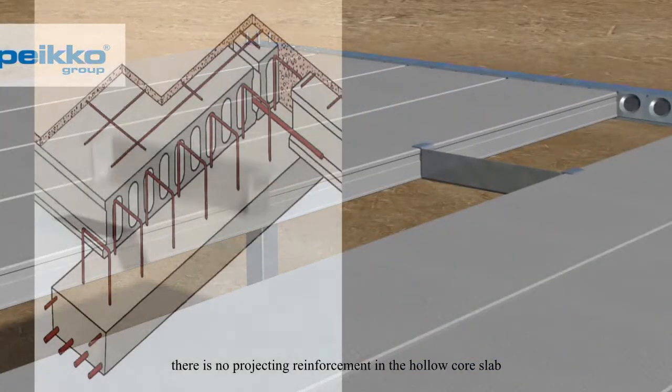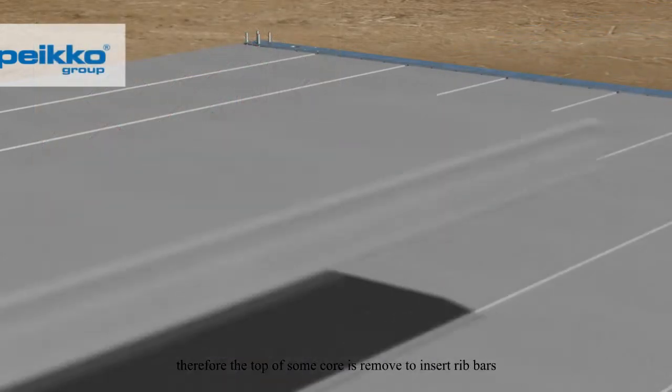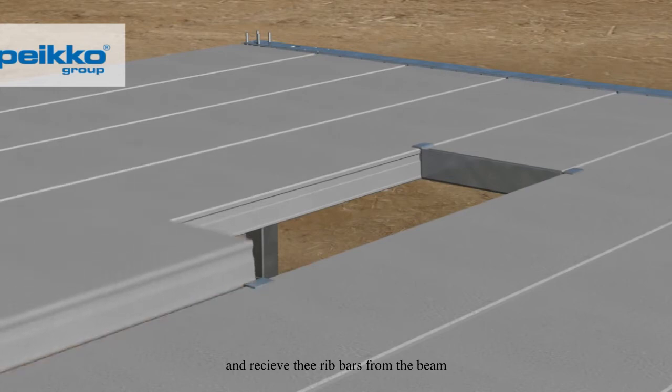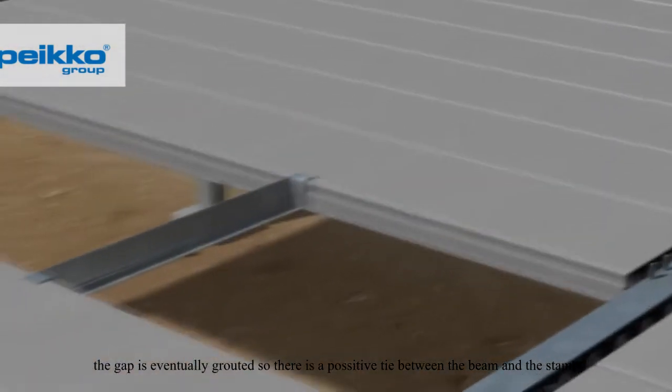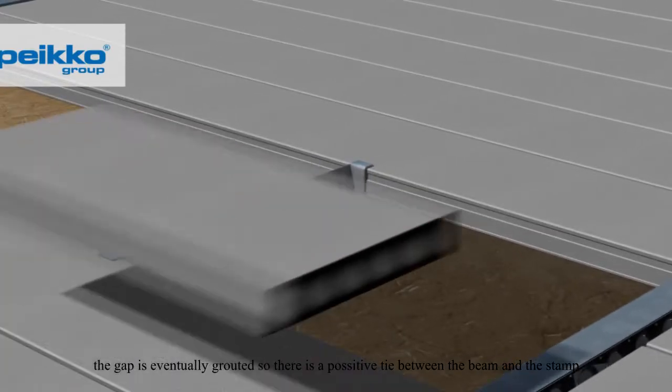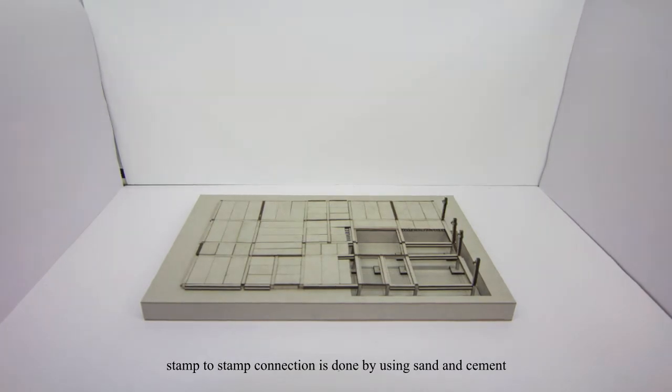There's no projecting reinforcement in the hollow core slab. Therefore, the top of some cores are removed to insert rebars and receive the rebars from the beam. The gap is eventually grouted, so there is a positive tie between the beam and the slab. Slab-to-slab connection is done by using 3-to-1 sand and cement grouting.